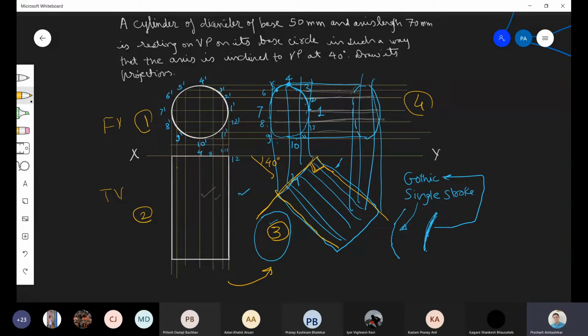Then draw a perpendicular line and then draw a line which is perpendicular to this and this, so that you will get a rectangle. After you get the rectangle, from this point to this point, take this much distance in compass and start getting the arc. Then from this point to this point, take this distance in compass, cut another arc. Then from this point to this point, take the distance in compass and cut the arc. Like this, you will draw arcs such that you will get this entire rectangle drawn here.